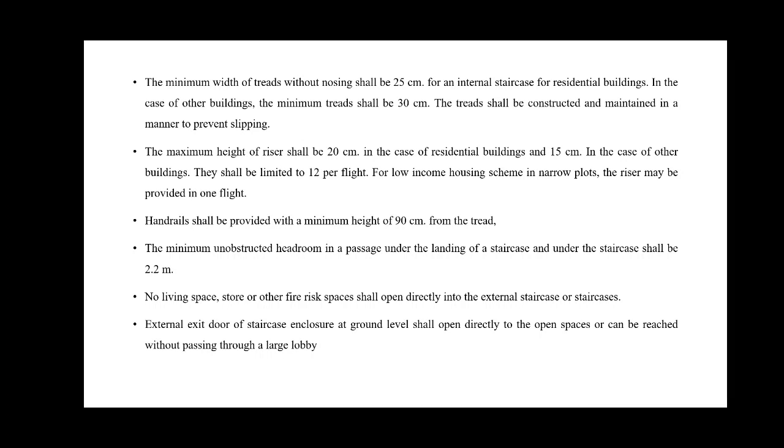The minimum width of the tread without the nosing shall be 25 centimeters for the internal staircase of a residential building. In case of other buildings, the minimum tread shall be 30 centimeters. The tread shall be constructed and maintained in a manner to prevent slipping.